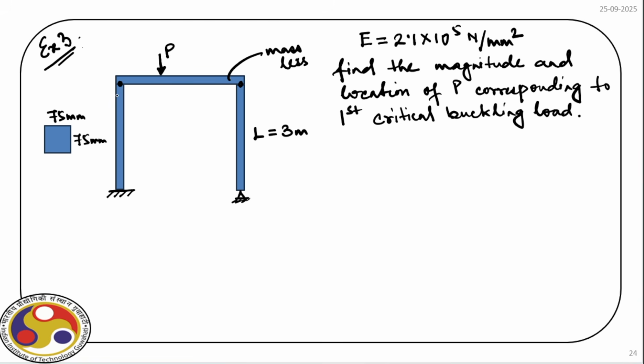That means the moment we apply the load P, it is transferred to the columns, and you can see these are the column loads. The reaction at this hinge point is upward. So if the reaction upward here is say P1, and here the reaction upward is P2, then obviously a compressive load will be acting over the column, right?